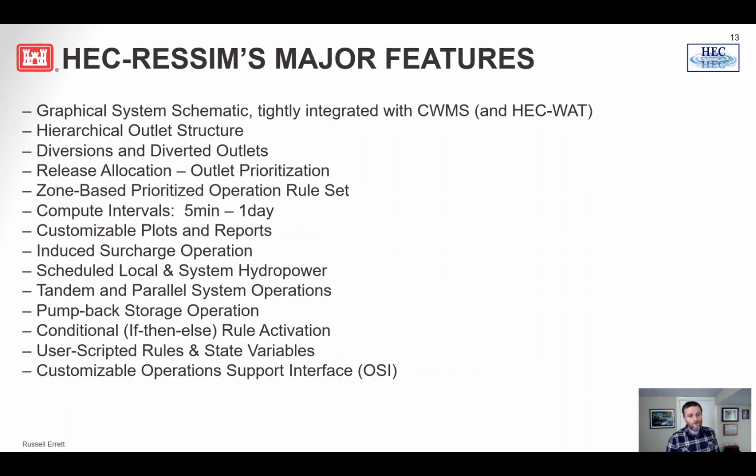Customizable plots, reports, induced surcharge operation we talked about, hydropower, again, tandem and parallel system operations, pump back. One of these things that are very heavily used, mostly because a lot of water managers and individuals that have set up ResSim models are very familiar with spreadsheets, is if then else. So you'll see a lot of if then else statements in there. So if these rules apply, if not, or else, then this is going to be the rules that apply. We went over scripted rules. State variables is another variation of the scripts. And then the customizable operation support, which again we're going to cover later on in this presentation.